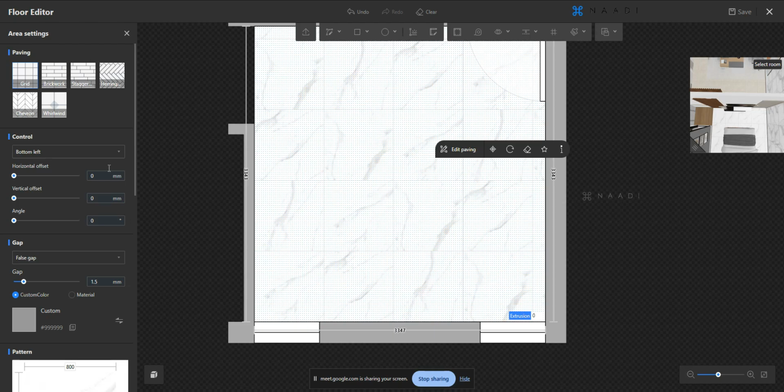Say there are different paving patterns available here. Can you see? In this common setting, we go for grid because that is how a tile is defined. But apart from that, you have your brickwork pattern, staggered pattern, herringbone, your chevron. All those are different paving patterns based on which the tiles could be arranged. All those could be configured here. Most of the time we'll be using this grid for your tiles. That is also there.